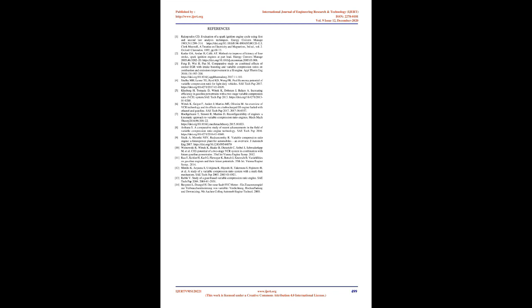It has electronically controlled electrical controllers, hydraulic valves, very few components and effective power output with great performance at the same time. A reduction of up to 5% in fuel consumption could be reached on the proposed conditions with the ideal instantaneous switching VCR system. Finally, it can be said that the transient switching system evaluation provided more reliable results for the evaluation, optimization, and development of variable length connecting rod VCR engines.